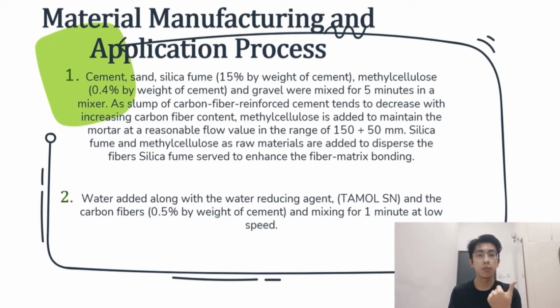First, cement, sand, silica fume, which is 15% by the weight of cement, methylcellulose, which is 0.4% by the weight of cement, and gravel. All of them are mixed together for 5 minutes in a mixer.